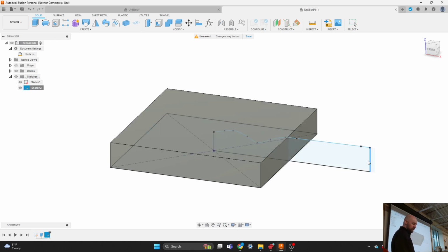Thankfully, because this sketch isn't constrained, we can expand it after the fact if we need to. We're going to revolve it around this center axis here, so it just needs to be longer than whatever our corner point is. I will make it longer. And here, maybe I'll make mine shorter, and then if other people have the issue, we can show them how to fix that problem.